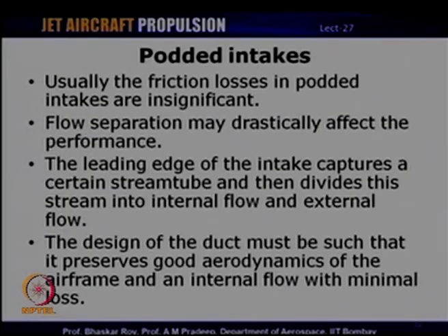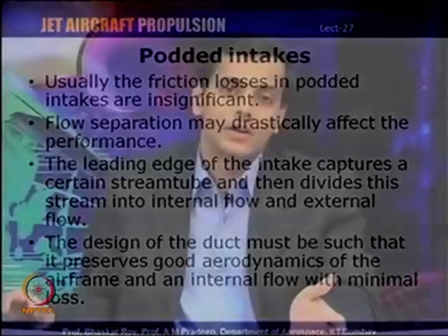At the same time, it also provides reasonably good flow at the engine face with minimal pressure loss, because pressure loss will directly affect the thrust developed by the engine, and therefore, the intake and the ducting associated with the intake must ensure that it not only preserves the good aerodynamic flow outside the intake or on the outer surface, at the same time it also gives a fairly uniform flow to the engine for proper operation of the engine,